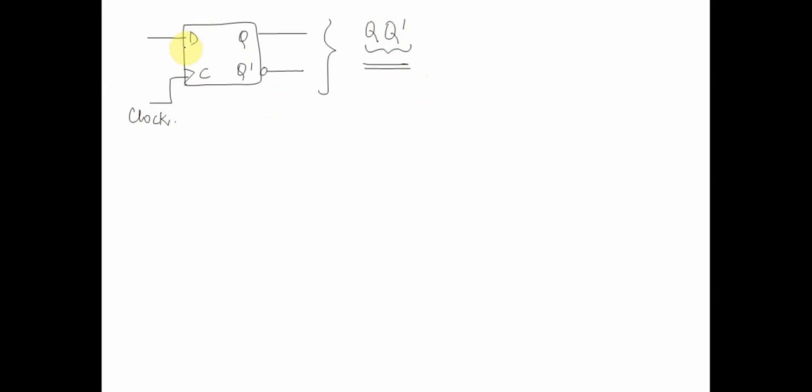So what could happen here is we could set the initial value synchronously at the next positive edge, but this actually makes the circuit design very difficult. That's why most flip flops provide direct inputs or asynchronous inputs that directly help us set or reset the circuit regardless of the clock event. Most circuits would have a pin, either a reset pin or a set pin. Based on the value supplied, if we make r bar equal to 0, we will change Q to 0, and this will ensure Q bar is 1.